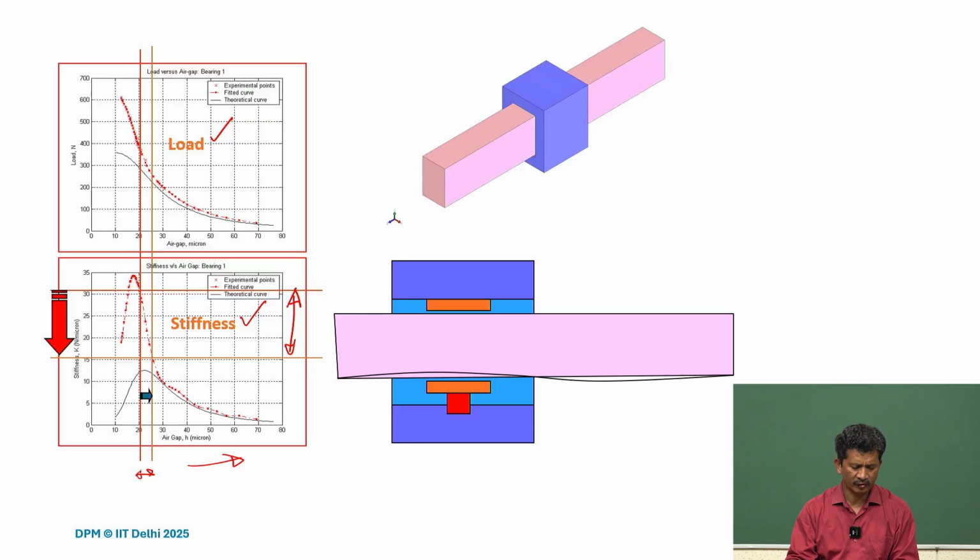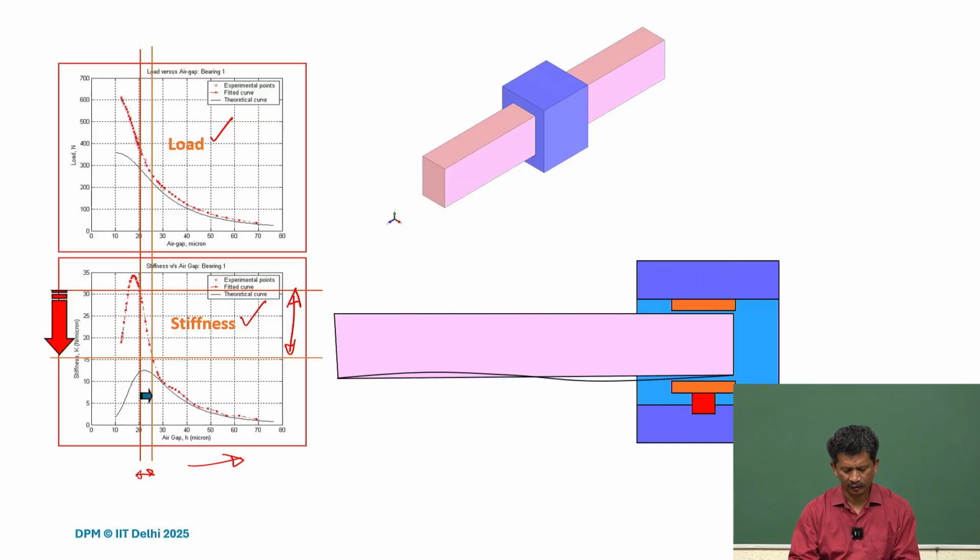Why is that? We can easily see with this animation. So this is the granite bar. Usually we use granite for this kind of application, for any precision application, mainly because of the structural integrity, the temperature variations and the moisture and all those aspects.